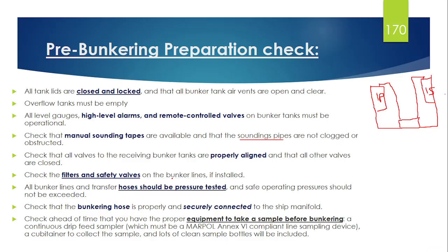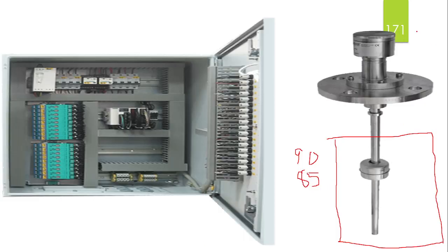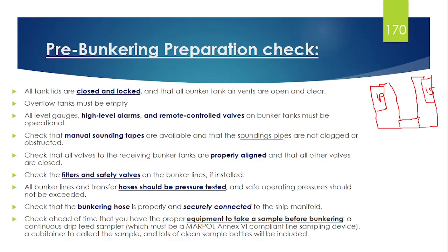So the major checks we need to do are: first, you should try out the high level alarm. Second, your overflow tank should be empty. Third, all the valves of the overflow tank and any other tank should be closed, and you should stop the fuel oil transfer pump. And then you should make sure that your sounding tape is clean and the sounding pipe is not clogged.